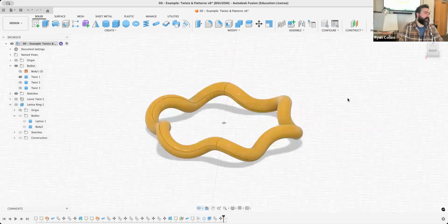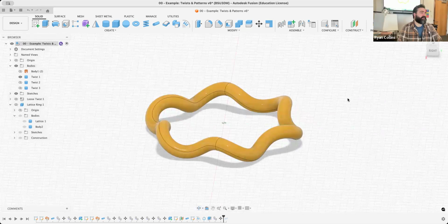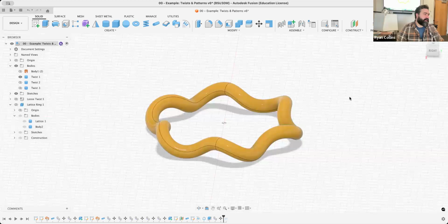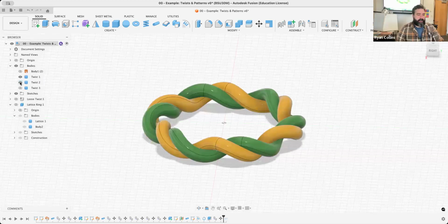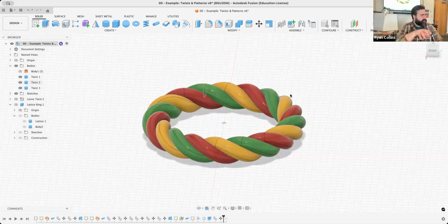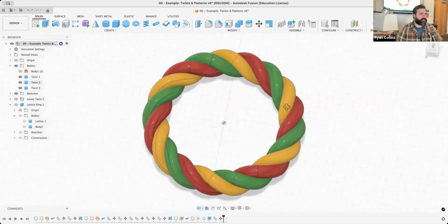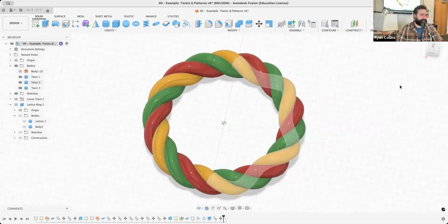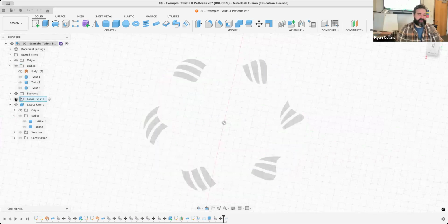Now, before we used a very defined sketch, making use of the 3D sketch tool to make ups, downs, and such and around. This is actually using the sweep tool with a slight variation on that. And then all I did was make a copy and a copy and just rotate them a couple of degrees, or the appropriate amount of degrees, so that they look like they're interlocking. They're just nested together.